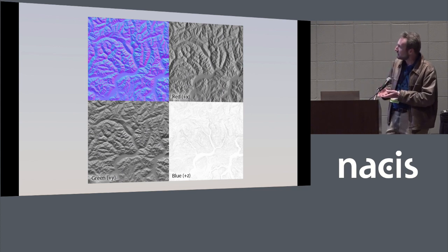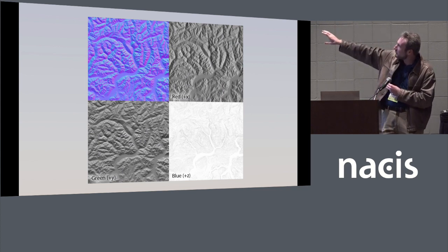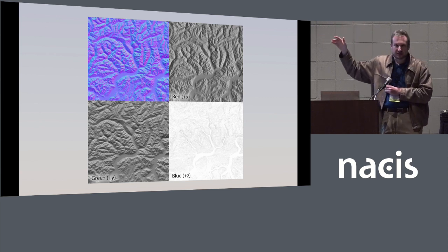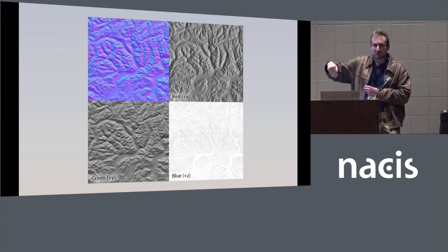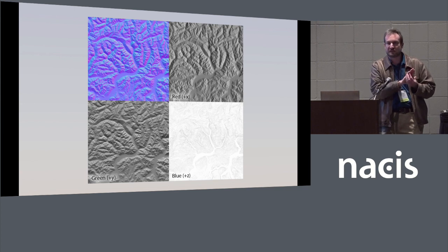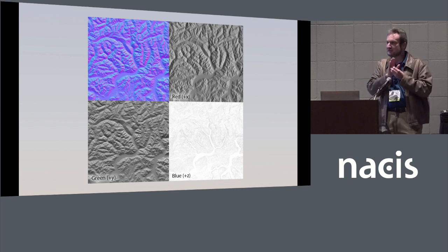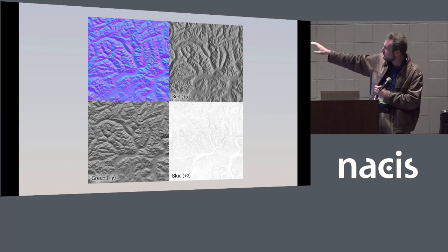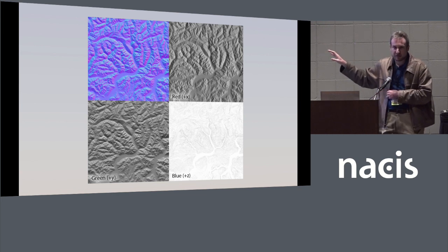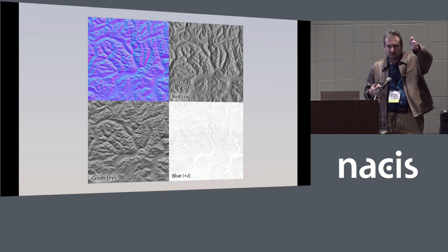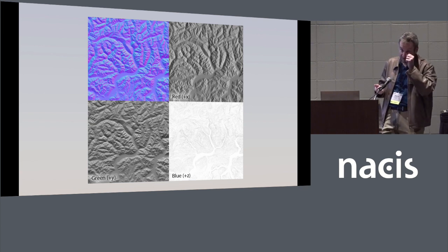So they have some interesting properties. If you break it back up into its component channels, it looks kind of like 3 sets of shaded reliefs, one lit from the east, one lit from the north, one lit from directly above. You can kind of also think of these as rasters that represent how much the surface is facing in any of these directions. Also notice that the blue band is much brighter than the others because on a top-down map, you're never going to see a face that is facing downward. So that z component is always going to have a value of at least 0.